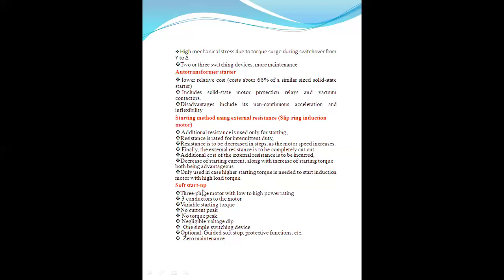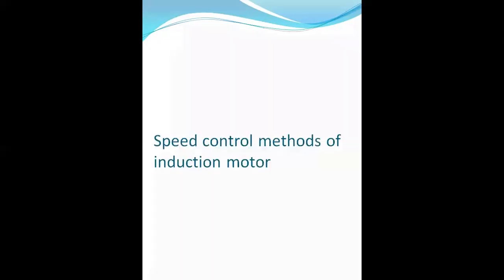So for the soft startup, it is for three-phase induction motors with low power rating, three conductors to the motor, variable starting torque, no current peak, no torque peak, negligible voltage drops, one simple switching device, optimal guided soft stop, protective functions, etc., and zero maintenance is required for soft startup.